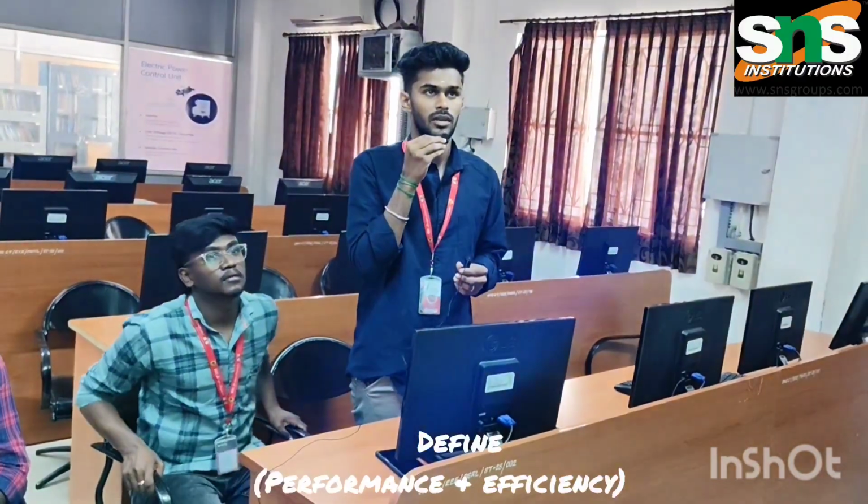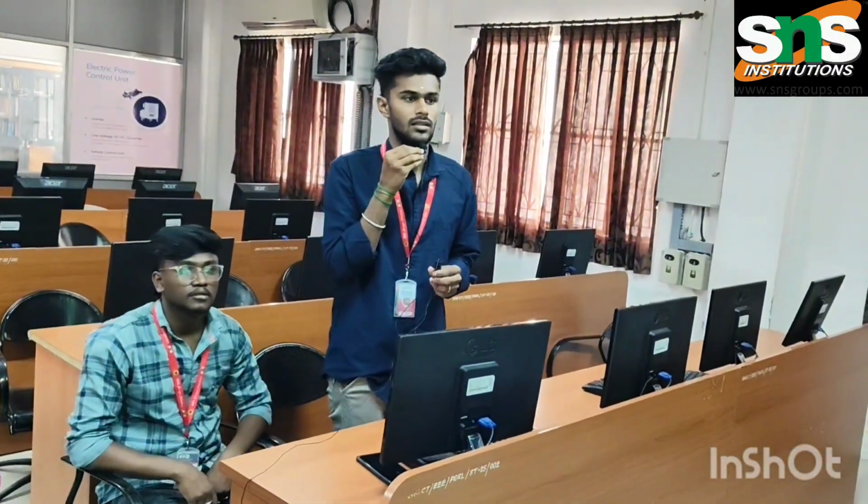Another define point is performance and efficiency metrics. There are two collector types, flat plate and evacuated tube, and the different collector types offer varying efficiency. A 4 square meter collector can produce approximately 2000 kilowatt-hours per year. Minimal annual maintenance ensures optimal performance and an energy offset of 50 to 80 percent of hot water needs.